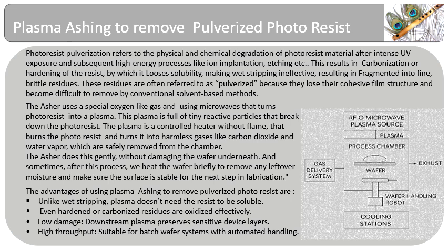After photolithography and etching steps, residual photoresist must be completely removed to prevent contamination and ensure clean surfaces for subsequent processing. Photoresist, when exposed to plasma, gets physically and chemically degraded. When wafers coated with photoresist are loaded into the chamber, the plasma reacts with the carbon-based photoresist material.